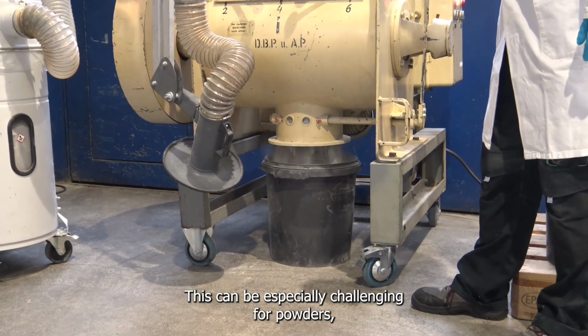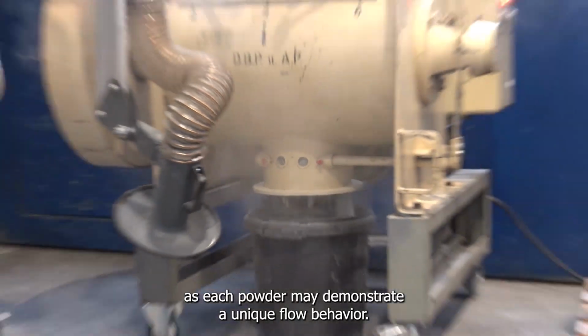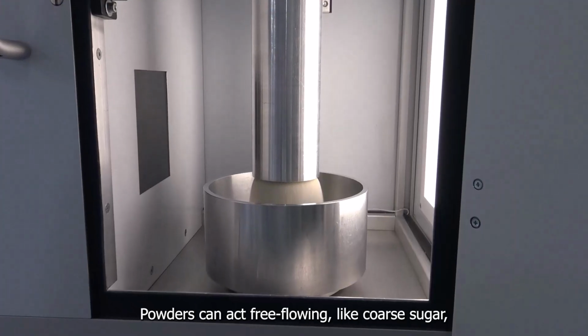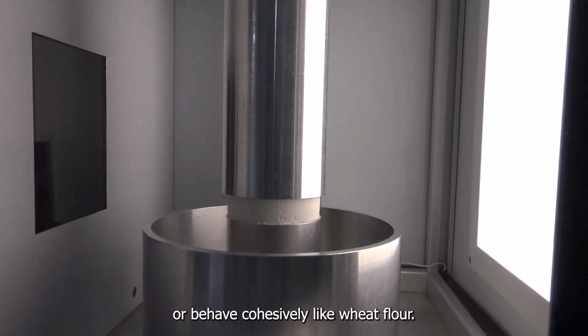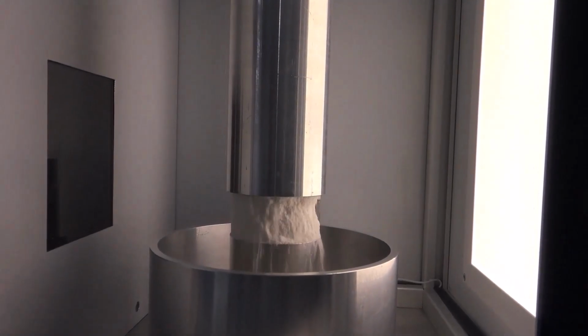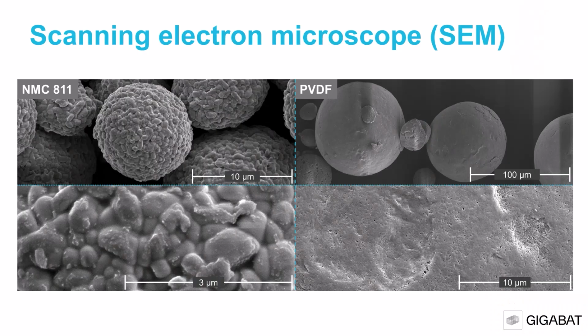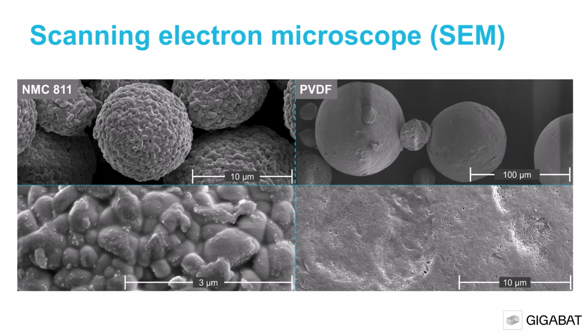This can be especially challenging for powders, as each powder may demonstrate a unique flow behavior. Powders can act free-flowing like coarse sugar, or behave cohesively like wheat flour. These behavioral differences are a result of the particle size, particle shape, material composition, and ambient conditions.